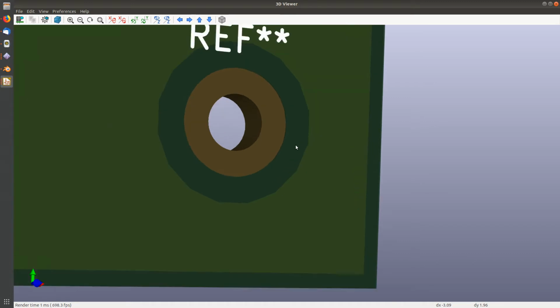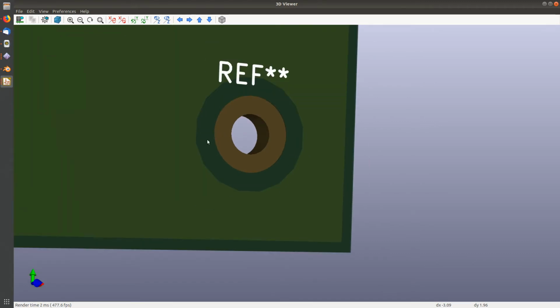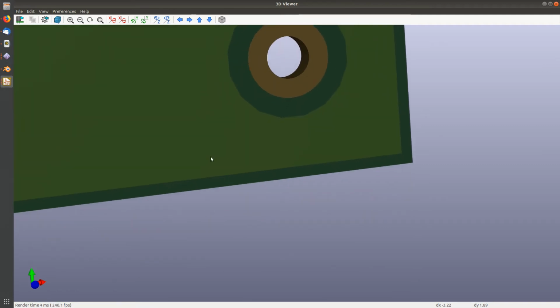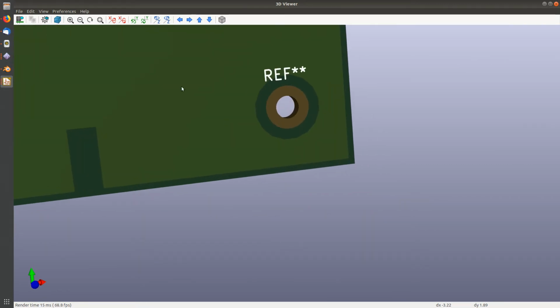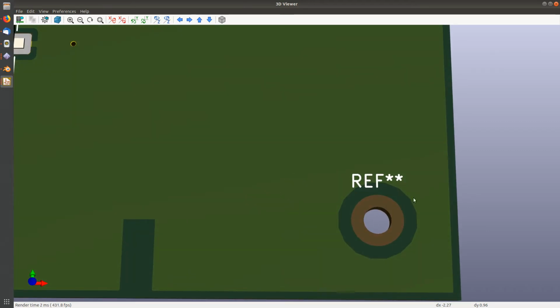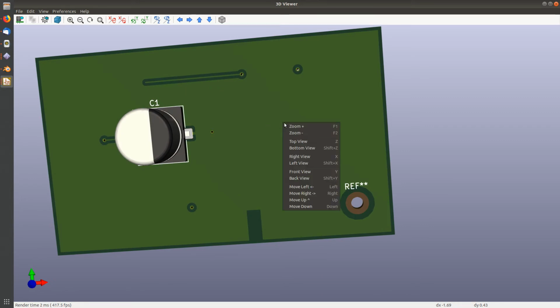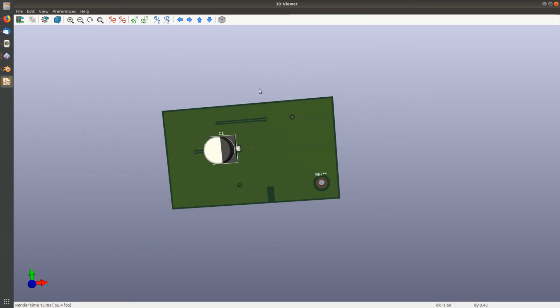So you always put a little bit of an overlap in here. In fact, you should go to your vendor and look up the manufacturer of your boards. They will give you a number and say, here's how accurately aligned I can put my solder masks. So give it more clearance than their worst case accuracy spec in their fabrication specs tells you they can do, right?